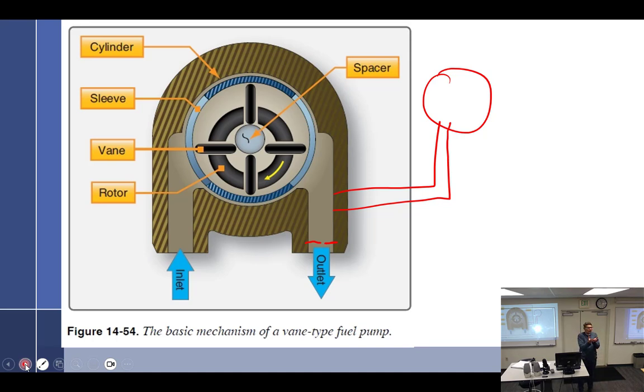It goes into the carburetor float bowl, and the float bowl starts filling up with fuel. What happens? The float goes up and the needle closes it off. And the pump is not that much, so it'll stop the flow of fuel. So everything's fine. You can just sit there and run the fuel pump all day. It doesn't hurt anything. Okay?